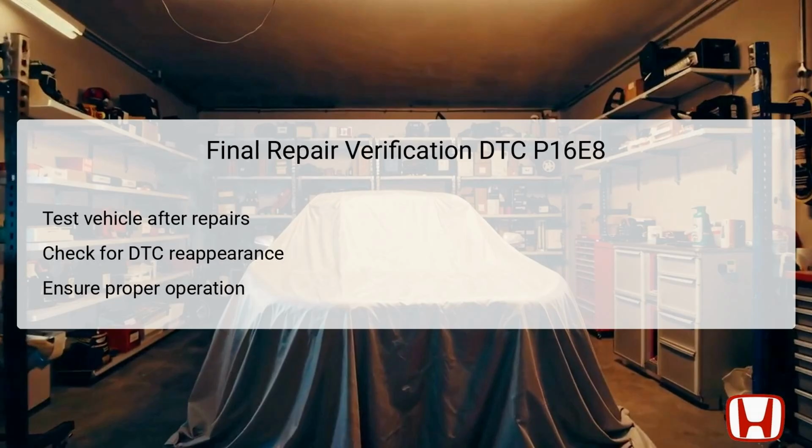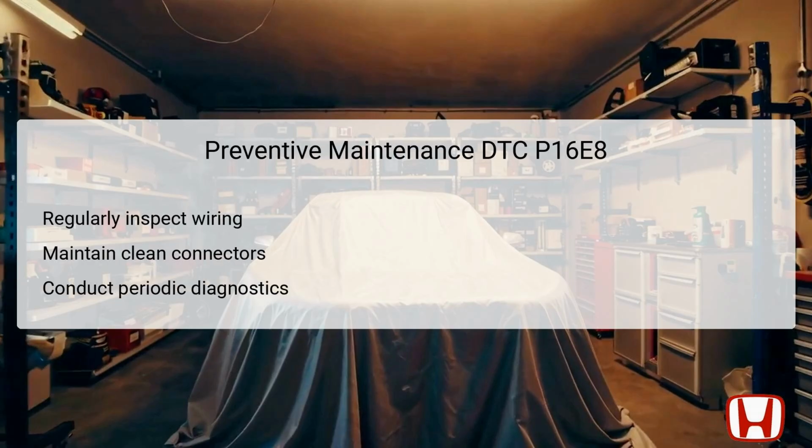its long-term performance. To mitigate the risk of encountering DTC P16E8 again, some preventive maintenance practices can be highly beneficial. This includes regularly inspecting wiring associated with the shutter grille and associated components to catch potential wear and tear early.